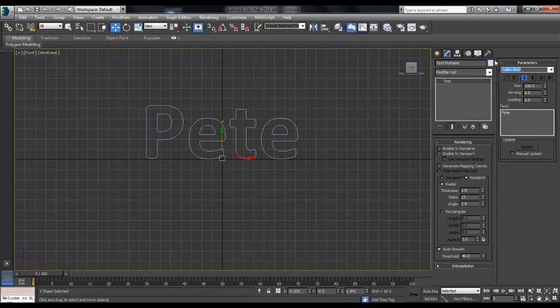Okay, so what we can do now is come in and adjust our size here just by clicking and dragging. Little tip here: wherever you see these little spinners in 3D Studio, you can right click to reset them to 0. I'll just type back in 100 here. You can hold Control to make them scroll much faster, and you can hold Alt to make them scroll much slower. Dragging down brings the value down, up brings the value up. I'm just going to reset that back to 100.